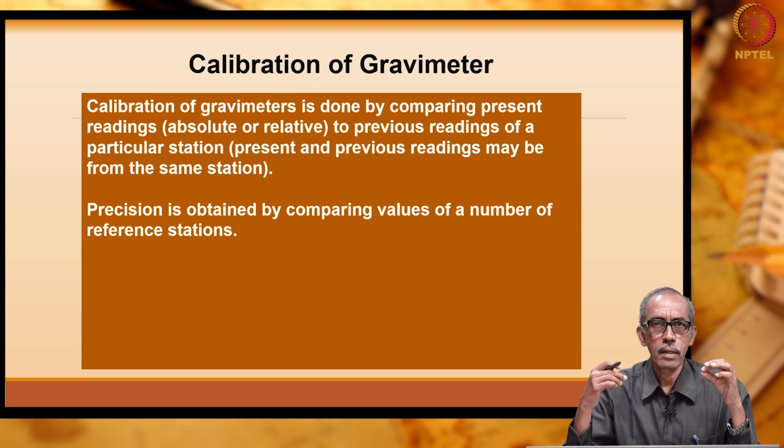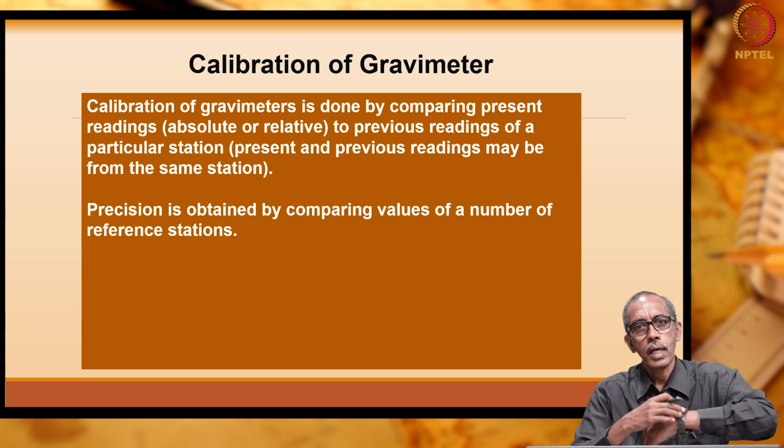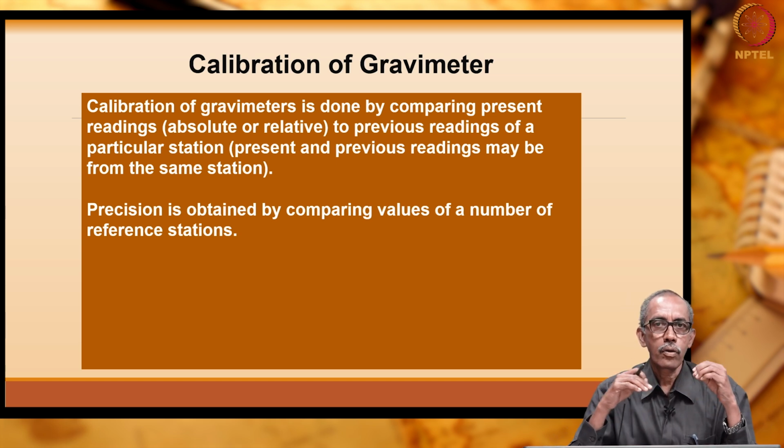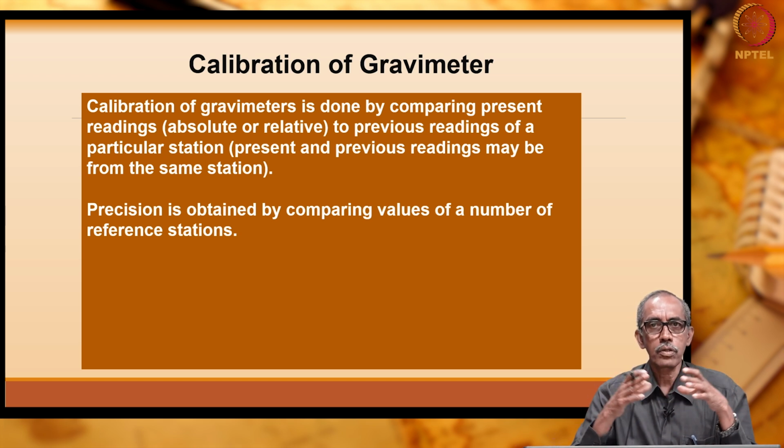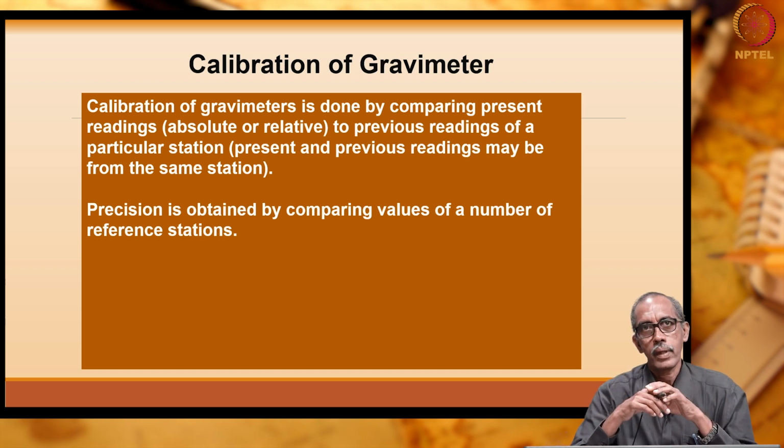So, what is calibration? For example, I am wearing a watch, and I do not know whether the watch shows the precise time. In order to make the watch show the precise time, the watch undergoes a process of calibration at the manufacturer's laboratory, isn't it? In the same manner, here we may have a very sophisticated expensive gravimeter with us, but before going to the field, we need to check and calibrate our own gravimeter.